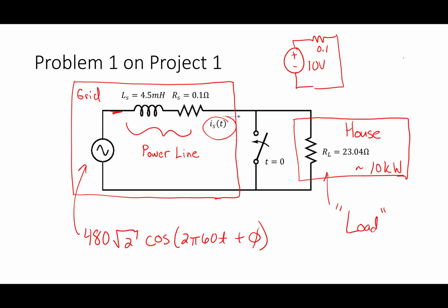This is the type of thing that you would do a lot of analysis with in simulation, because, like I said, you don't really know what those values LS and RS are, and it's annoying because the transient clearly depends on the initial condition. So I usually have to run a number of simulations. In the real world, you don't usually solve a differential equation like this for one set of values. Usually you're doing it over a range of different values. It's easy for a computer to script it and run all these different conditions and show me all the different results. So it's again a typical real world example. This should be really similar to what you have in problem 1. So hopefully this will help you guys.